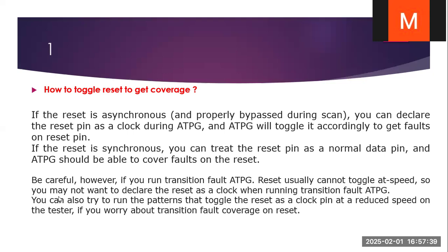So you may not want to declare the reset as a clock when running transition fault ATPG. You can also try to run patterns that toggle the reset as a clock pin at a reduced speed on the tester, if you worry about the transition fault coverage on the reset.